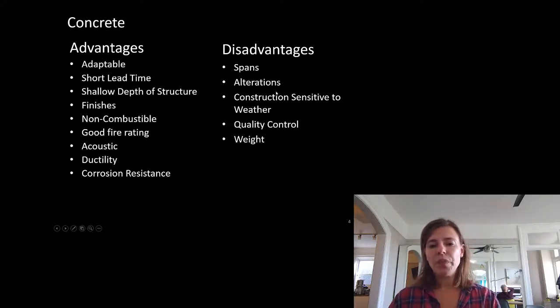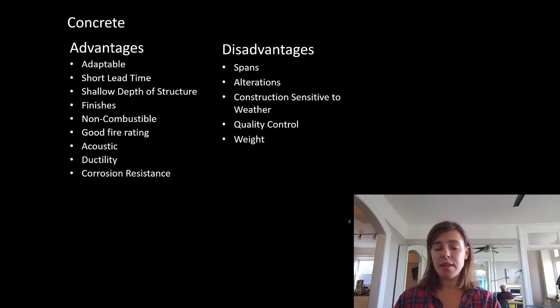So, concrete has some flaws in that it works really well, but often we kind of limit it to some smaller spans. So if you want those really large span buildings, it doesn't mean you can't do concrete. It might mean you have to understand the cost and the expense of that, because it's not inherently geared to that. Or maybe you need a hybrid system where you introduce other elements.